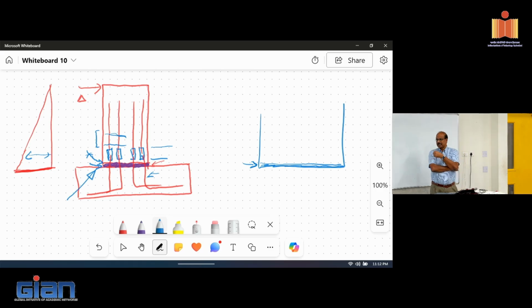So when you do details like that, you have to check to make sure that the adequate reinforcement is actually going through to prevent any sliding. In some cases, we have mechanically eliminated the shear sliding, but it's a possibility. We talked about putting UHPC in the ground. Anyway, we got crack to happen there. No, it will develop on the top of the UHPC layer. Yeah, you can't avoid that crack, no matter what you put in. But maybe you can limit the crack to the service stage problem.